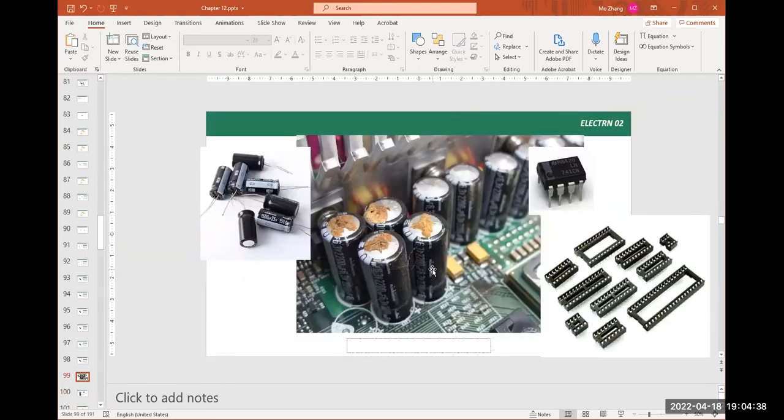And also, a capacitor is, in my opinion, the number one fragile thing. So if the circuit is not working suddenly, such as it worked 2 hours ago, now we try to use it, the monitor light blinks, however the screen doesn't turn on. It's just a black screen with a blinking light there. And we try many features, try to troubleshoot, doesn't work. There's a higher chance the capacitor inside is burned, exploded, or broken. So you may need to replace the capacitor, and then hopefully that monitor goes back to work.